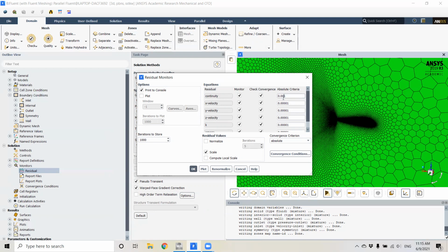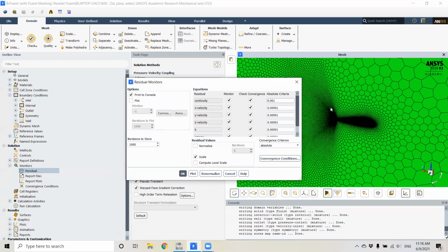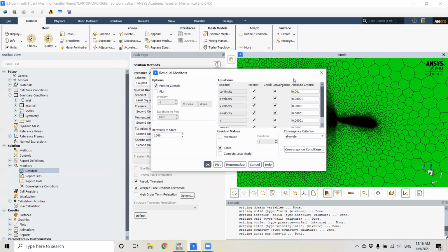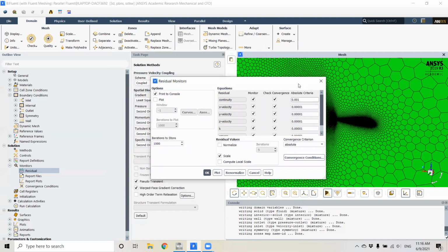I'm not sure why, but doing some research in forums, the Ansys forum and Google, one of the staff mentioned that if you have something like a 10 to the minus 3 continuity residual and you have convergence in the variables that you're looking at, that's a reasonable convergence criterion.